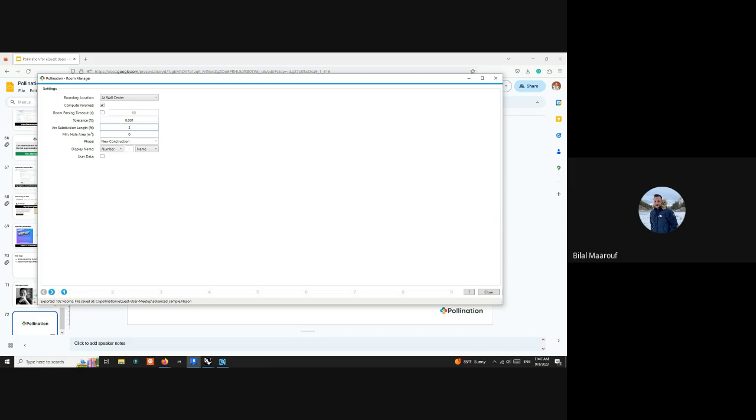My question about the HVAC wasn't necessarily about modeling HVAC systems, but my comment is eQuest is very inefficient when you want to assign and reconfigure systems to zones. So as part of the export settings, can we have the user select whether you want all zones to have a system per site, system per floor, or system per zone? Because like I said, we're saving time on the geometry end, but that would add a lot of stress on the HVAC assignment end. It's inherent in eQuest. So I would just suggest that.